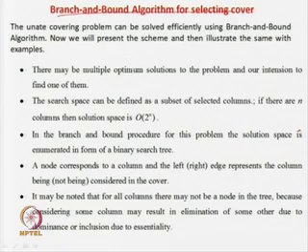So, the solution which will have the minimum number of prime implicants will be your solution. Now, even if you can go for a finer way of thinking, then for each of the prime implicants individually you can put a weight, like it can be the number of literals involved in a prime implicant. Like if x is a prime implicant, it has a weight 1 say, and if a prime implicant is ABCD, it has a weight of 4 kind of a thing. So, you can devise different types of weights.